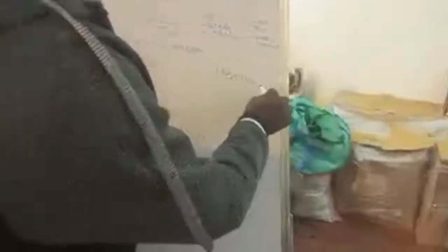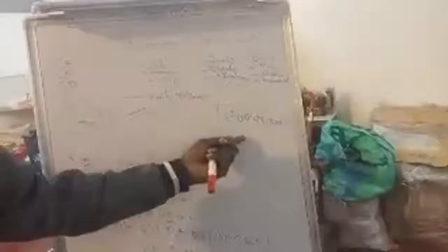And now, because I've finished cutting, if I want to do finishing, I can include my code here, G70 for finishing, and then I can put P. Where was I starting cutting from? P42. Where was I ending? Q45. This will mean that at the end of cutting, my program will do a finishing cut so that it removes 0.5 and 0.1 millimeter.